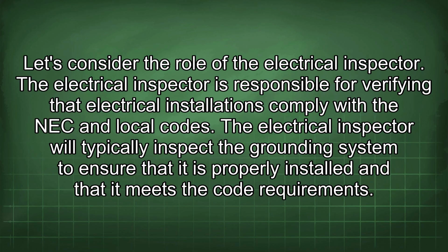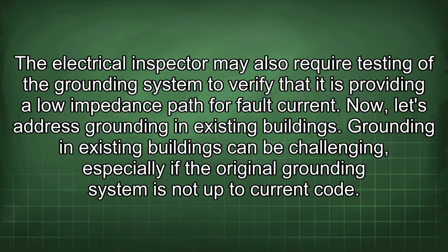Let's consider the role of the electrical inspector. The electrical inspector is responsible for verifying that electrical installations comply with the NEC and local codes. The electrical inspector will typically inspect the grounding system to ensure that it is properly installed and that it meets the code requirements. The electrical inspector may also require testing of the grounding system to verify that it is providing a low impedance path for fault current.